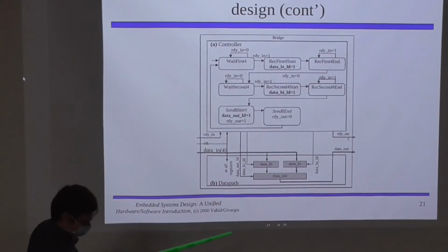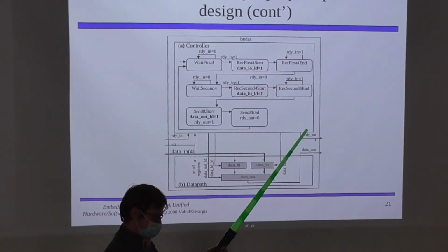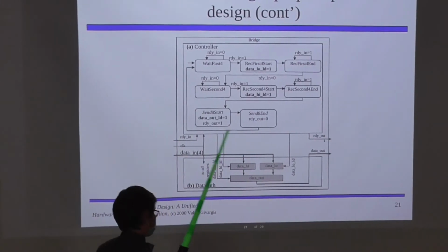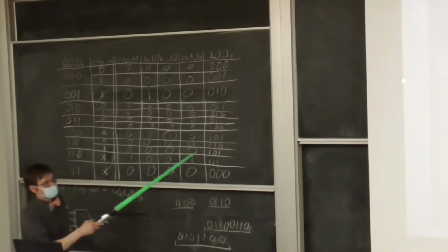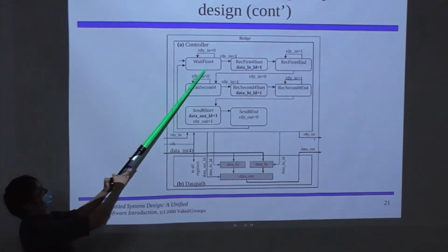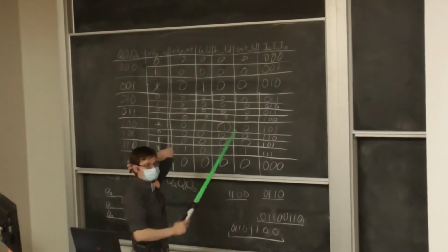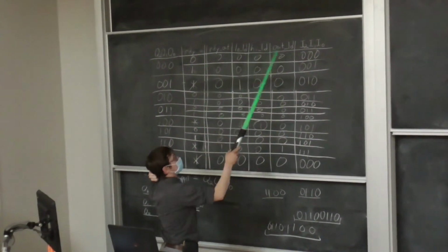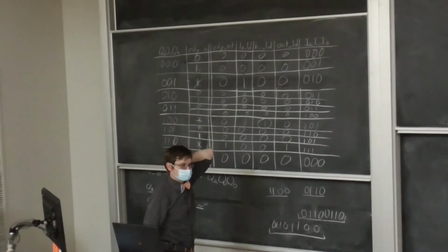Right? Because when it's 0, it loops back in. Exactly. The whole execution of the algorithm is dependent on what the state of ready in is, right? So we have to account for it. If it's 0, in this case, we loop back into the current state, right? Yeah. So even not worrying about the fact that all of the registers we're not doing anything with them, in that case the next state is the same as the current state. Okay. Make sense?